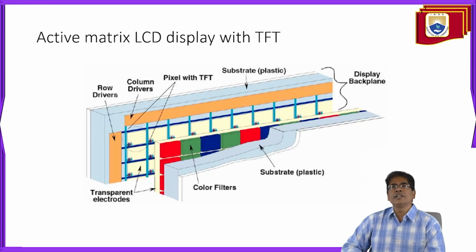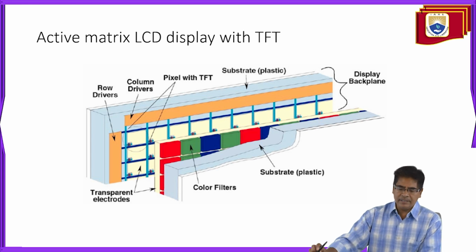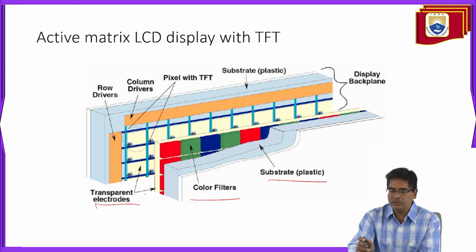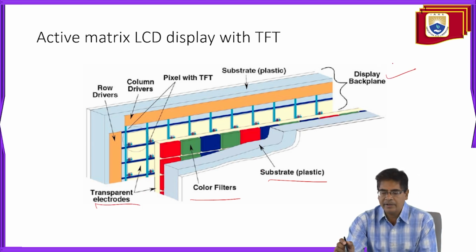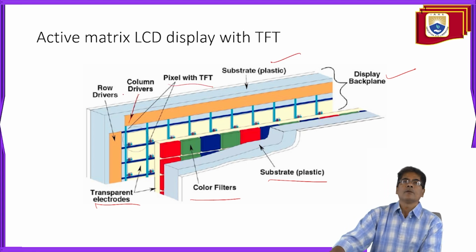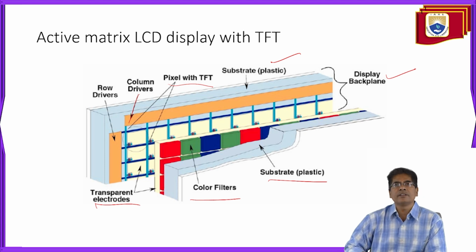So this is the active matrix liquid crystal display with thin film technology. We have color filters, plastic substrates, and transparent electrodes. We have the display black paint, the plastic substrate, and the pixel with TFT, driver columns and row drivers. These are the active matrix liquid crystal displays with thin film technologies.